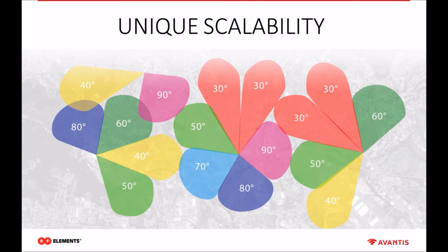But this is one way. Scalability is also when you have customers concentrated in one place, for example, a village. It doesn't make sense to cover the whole 120-degree sector and also the areas where you don't have customers. It makes much more sense to cover only the area where you have customers. So with symmetrical sector antennas you can, for example, pick a 50-degree symmetrical sector antenna, so you will just cover your customers.